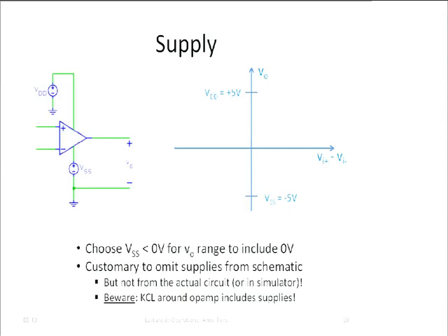I mentioned the only non-ideality that really is important, especially in the laboratory, that we'll consider, is the supply voltage, right? If the gain of the operational amplifier is infinite, then really, this is the gain, right? This is extremely steep. Actually, the slope of this line here should be infinite, or the line should be vertical. I didn't draw it quite vertical because otherwise you can't see it anymore. Well, in practice, it goes up only up to the supply voltage of the operation amplifier like this. Okay? So that's the characteristic.